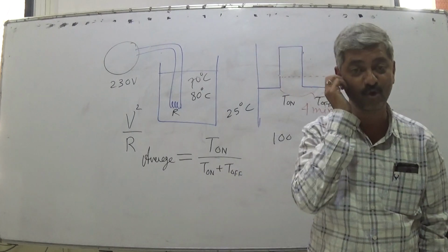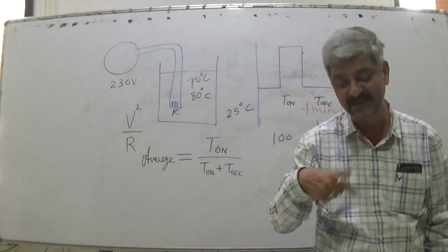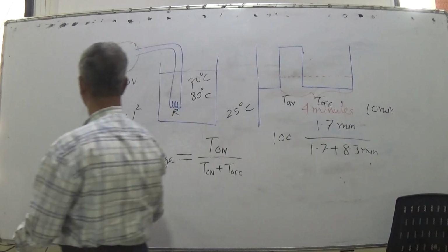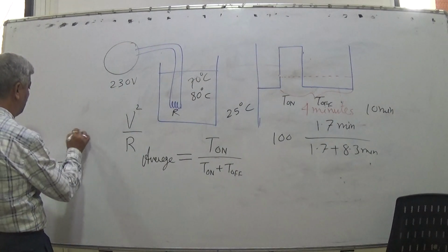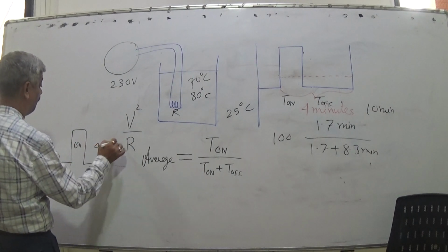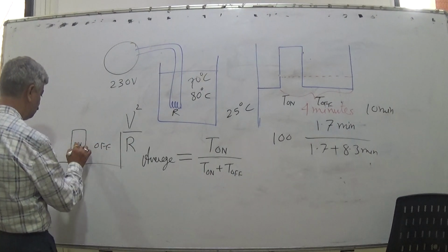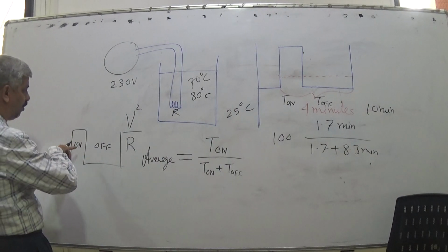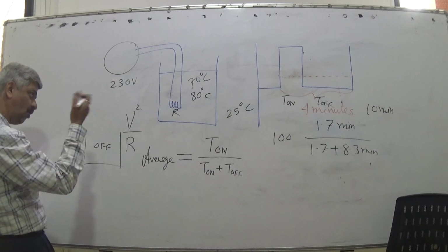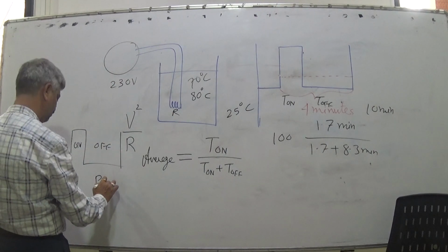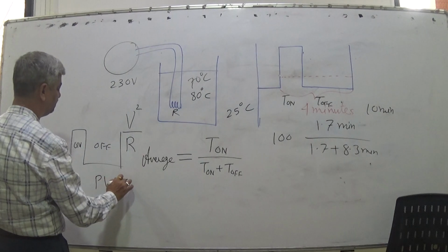Therefore there is no need for a DAC. The DAC function is indirectly managed by changing the on time and off time of a digital output itself. A digital output pin driven on and off based on some logic is a normal pin, only managed separately.